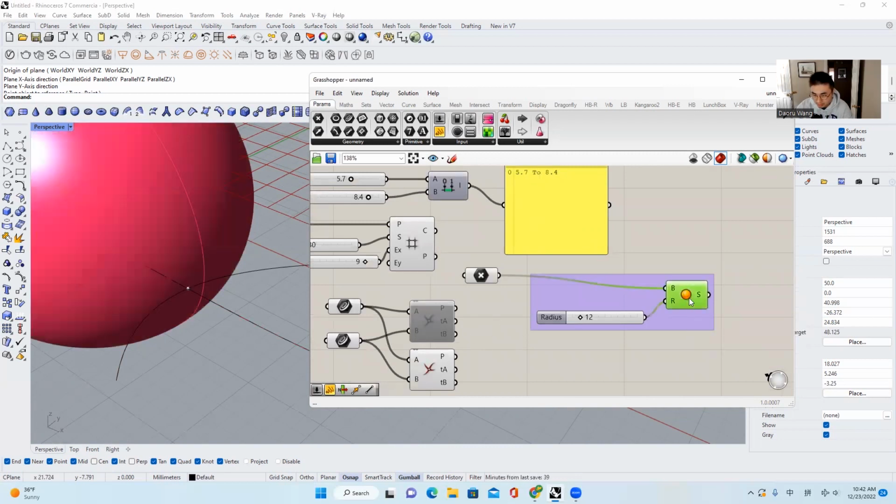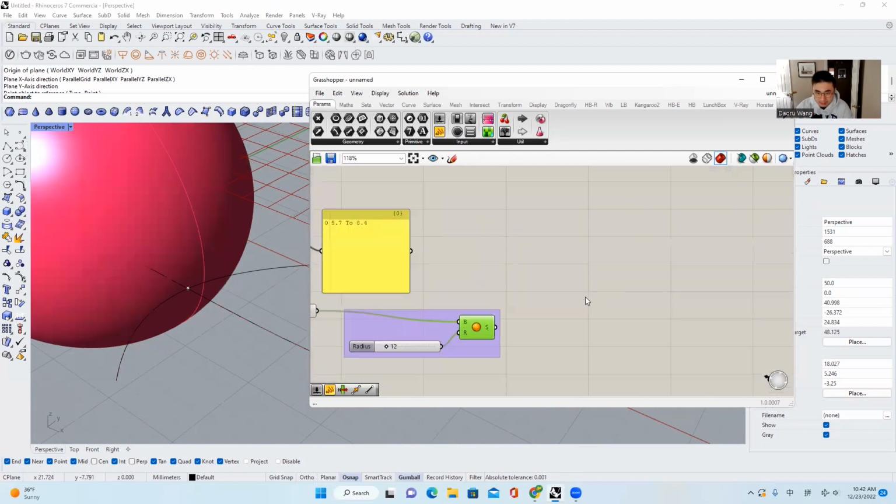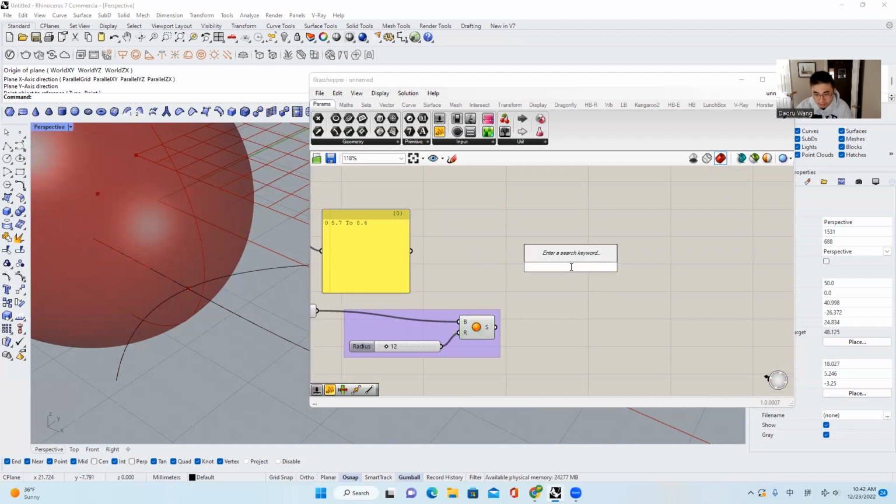The last thing I want to show you again is right click. You can preview, enable, bake in a different manner. Again, a lot of things are repetitive, but they have certain differences in the details of controlling. The last thing I want to talk to you about is the search tab. If you want to find some specific component but you don't remember where it is, you can just use search. For example, like addition, you can just type in ADD and you can search for this.